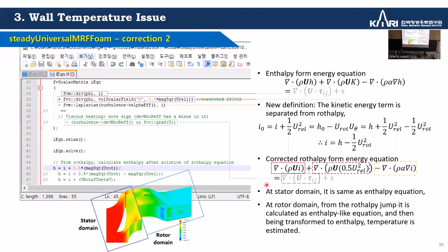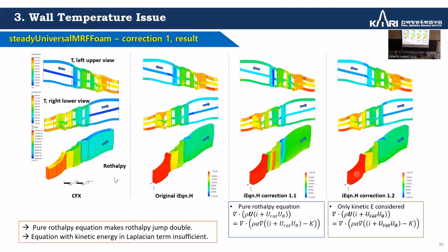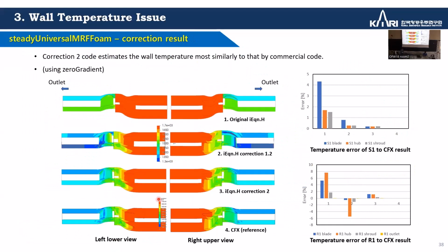You use the rothalpy I here, mimicking the enthalpy form of the energy equation, and you use the kinetic energy using the relative velocity, and then you can get the right solution, in my eyes.